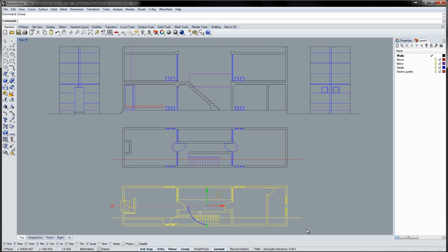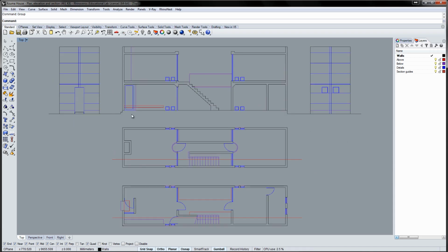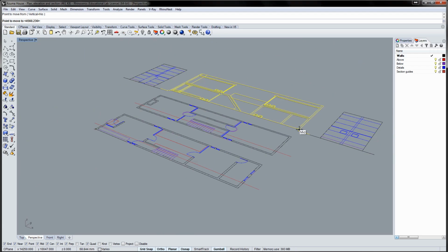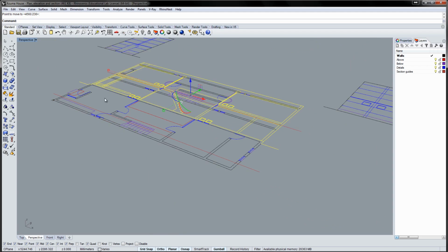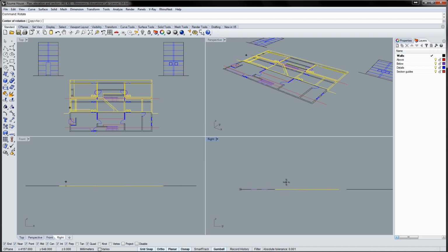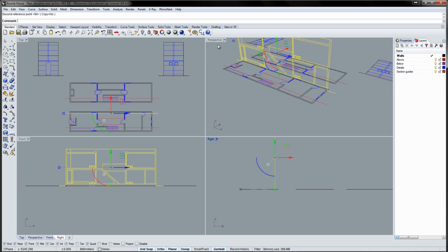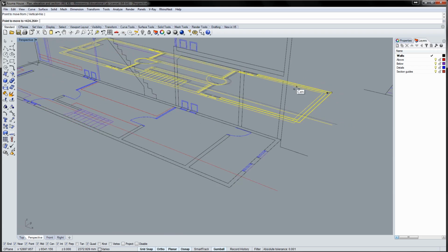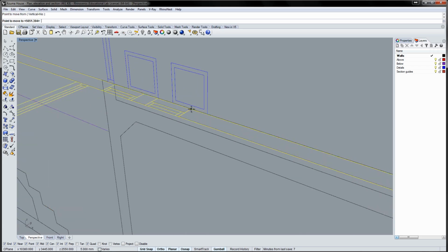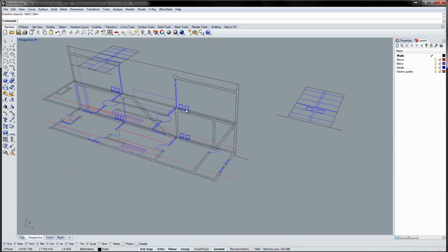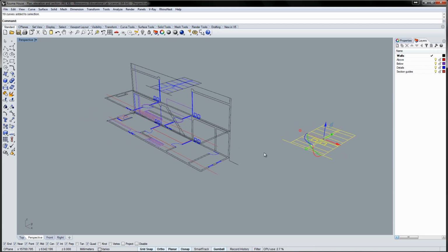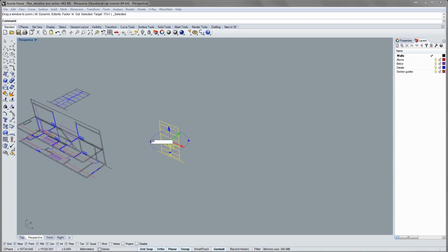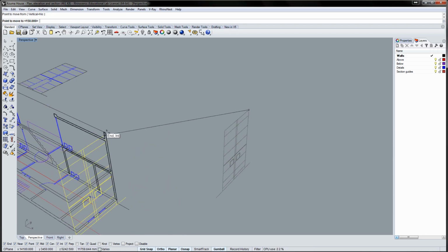Group the drawings individually. Rotate the drawings. You can rotate in a 2D viewport. Move the drawing to its desired position and be precise. You can also rotate using the gumball. Rotate and position the drawings so they form a matrix.